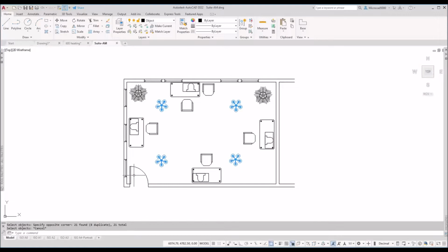Now, what if I wanted to avoid those light fittings? Well, in the later releases of AutoCAD, in the last few releases, if I go into the erase command, you get this lasso. Now, if you hold your mouse button down instead of releasing it, and go in a clockwise direction, you get a blue lasso. You can put a lasso around the objects and avoid some other objects. So I want to avoid the lights. So by holding that mouse button down, you can avoid those light fittings.